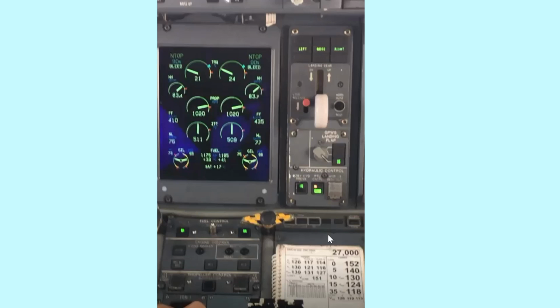Okay, and before presenting to you this video, I have tried approaching with the autopilot engaged until 1,000 feet AGL and thereabouts, and I was studying which torque value here will give me the Vref I need. So for example, if I was coming in with 28 tons of landing weight, I will have here around 28% or around 29% or 27%. If I was coming with 26 tons, for example, somewhere here it will be 26%, 27%, somewhere around there.